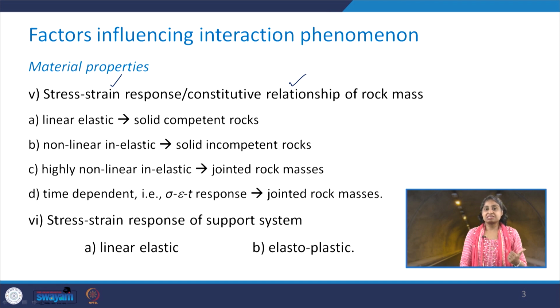This we have discussed earlier, but just for the sake of continuity and completeness, we will take this up once again. You know that solid competent rocks will behave in a linear elastic manner. That means their stress strain response is going to be linear elastic. In case you have solid incompetent rocks, then the behavior is going to be non-linear inelastic.